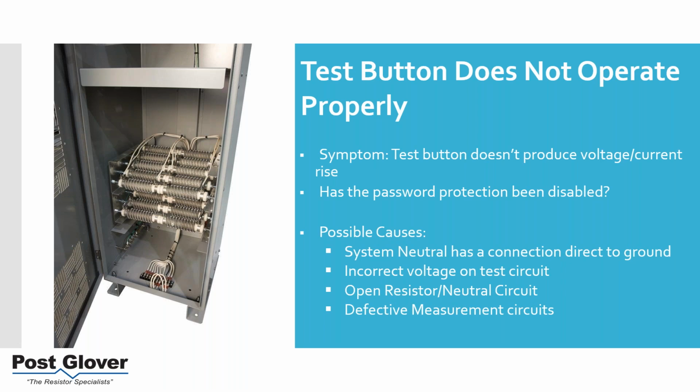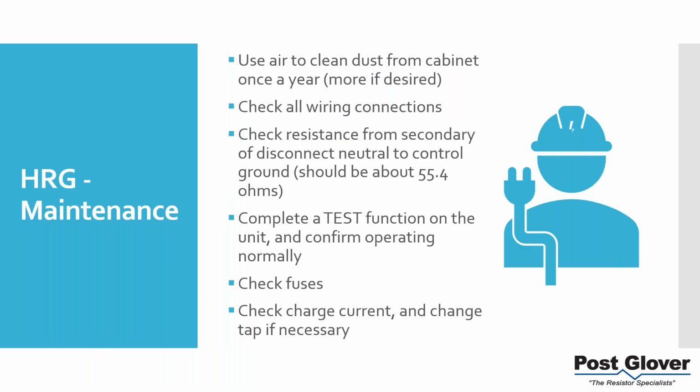You could have incorrect voltage on the test circuit. Open resistor, it's common. You usually would have an alarm for that, but all these things could happen. So you want to make sure that you're paying attention to the test button when it does not operate properly.